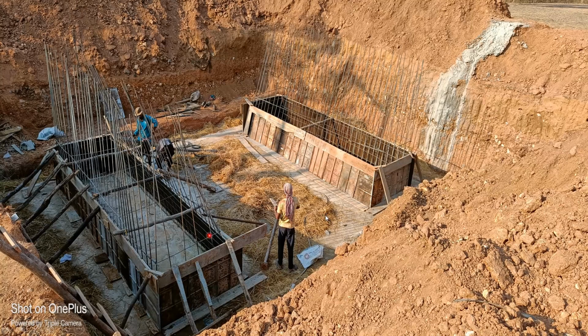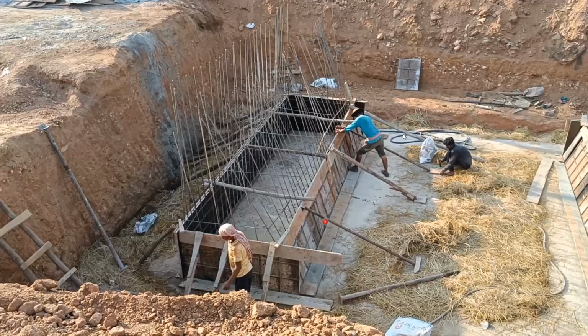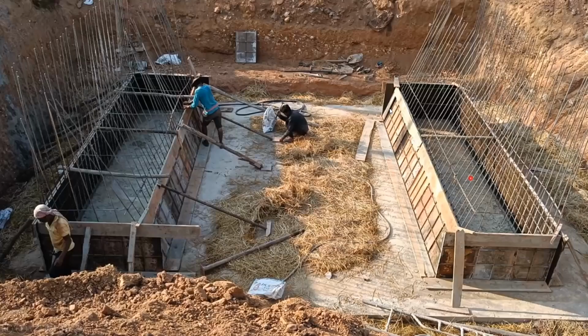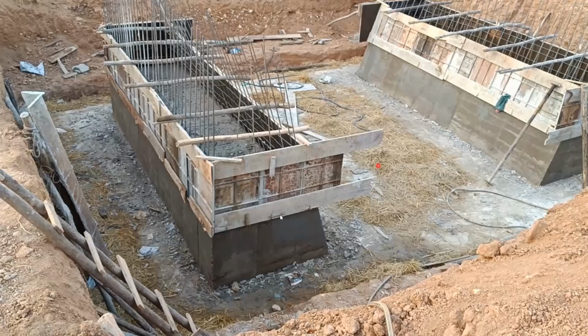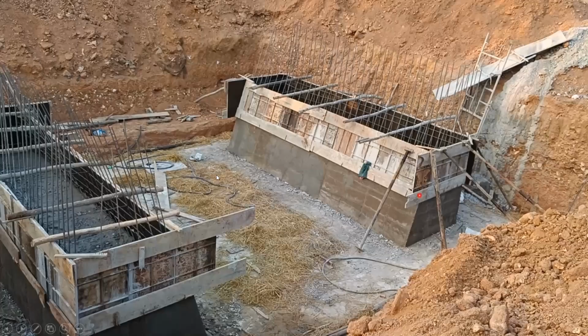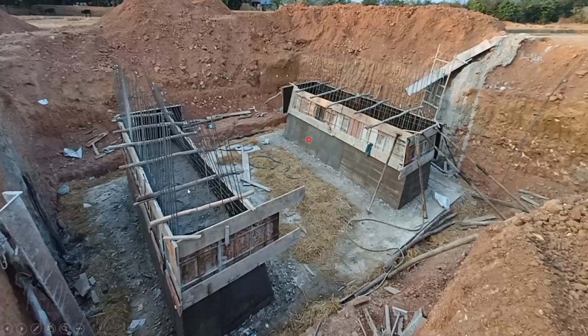And then what will happen after that? Once that is done, everything is ready now. This will be a kind of inclined here, because through this only your water is going to flow later. Got it. Then we have done the casting of this. See, this is the first layer casting what we have done. We have done the de-shuttering, and we have lifted it again. So this is my second lift. Again in the second lift, we'll do the concreting. Okay, again we'll do the second layer.